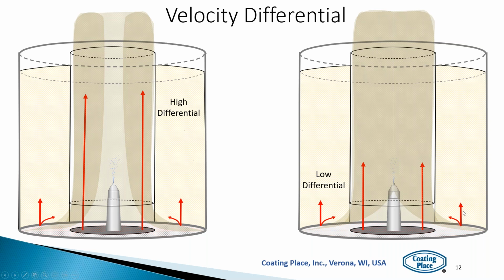Generally, if you're doing things like granulating with a bottom spray Wurster, the velocity of the air in the upbed is going to be roughly 3 to 5 times what it is in that outer bed to fluidize. And so when doing that, your particles don't feed in and necessarily go pneumatically transport directly up into the expansion chamber. They might, but they get into a wetter part of the stream where they're getting well wetted,